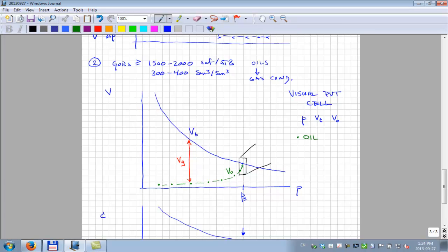You're going to be extrapolating this volume, that volume, maybe this volume, these three volumes, to where it crosses the total volume curve. And because it can be quite nonlinear, well, it won't be too bad, but you'll basically identify that, okay, that's my bubble point volume there.